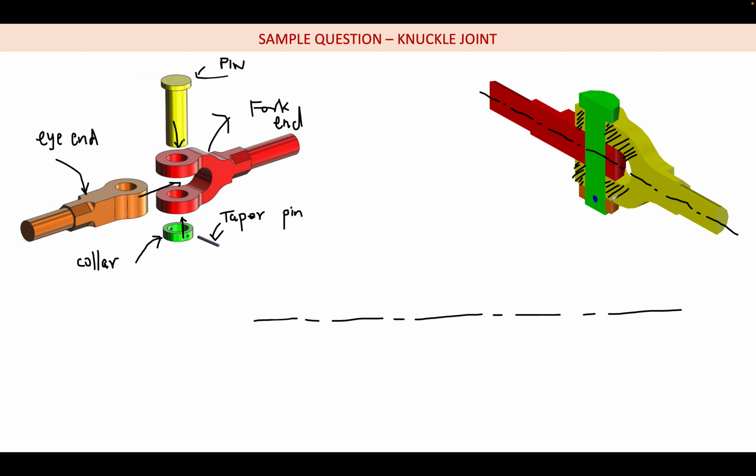Here when we come up to this part, we are going to section up to this part and draw some kind of a break line. Why we are not sectioning this octagon and shaft is, as I already told you, the section plane is passing exactly through the center of the shaft, so this shaft part we are not showing.